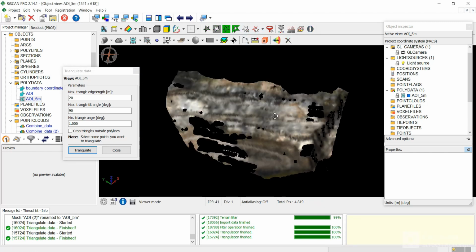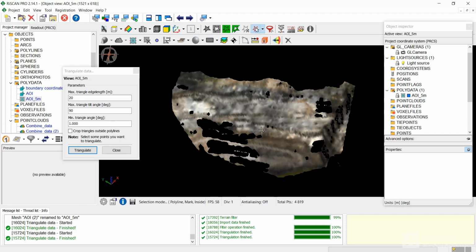Again I will deselect the point and start selecting the holes. You can't select the entire data. This is very important. I can't just select the entire data again, increase the maximum triangle edge length and run the triangulation process. No, because the points where I have put the maximum triangle edge length 10 were already triangulated, so it will re-triangulate them, and the shape and size of those triangles will change, and this will significantly affect the output volume.